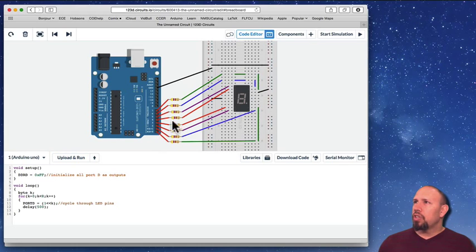So notice I've got all these resistors connected up, and I have ground going through here. Okay, that ground connects here. So remember that this is the common cathode circuit. So notice it says COM here. That refers to a common cathode. And so I also have a COM over here, and so both of these are ground. So this line here is all ground. This line over here is all ground.